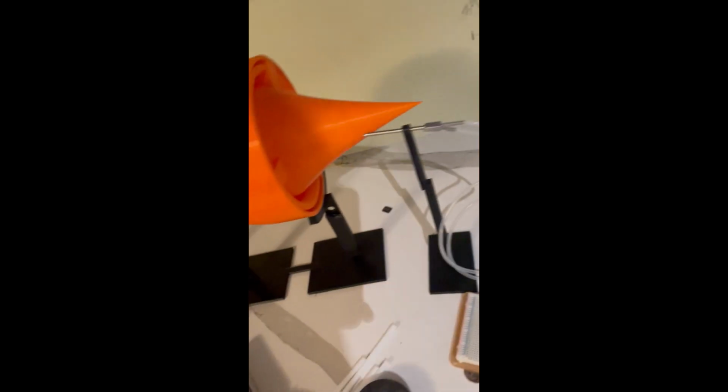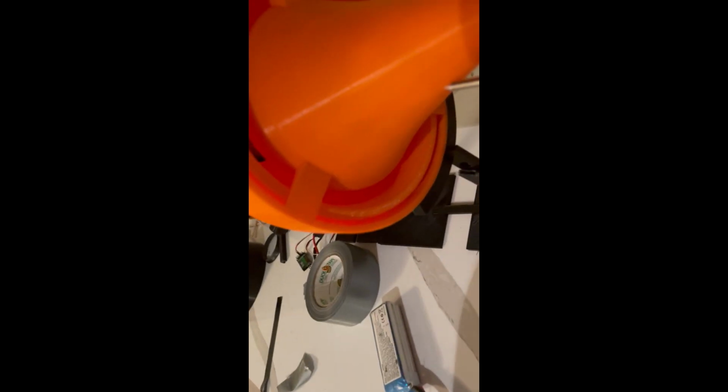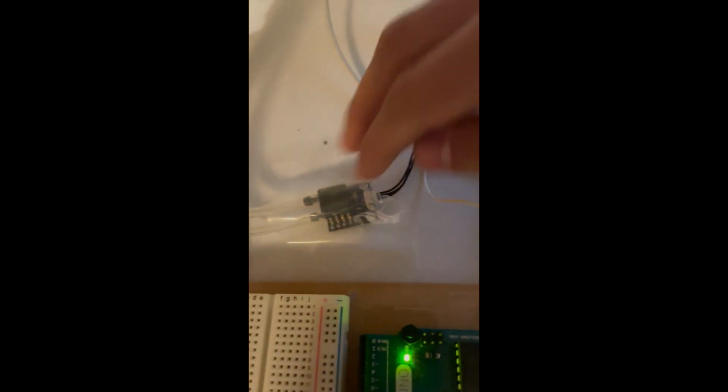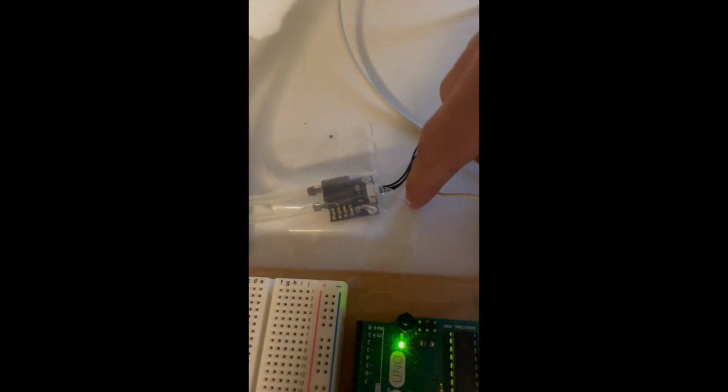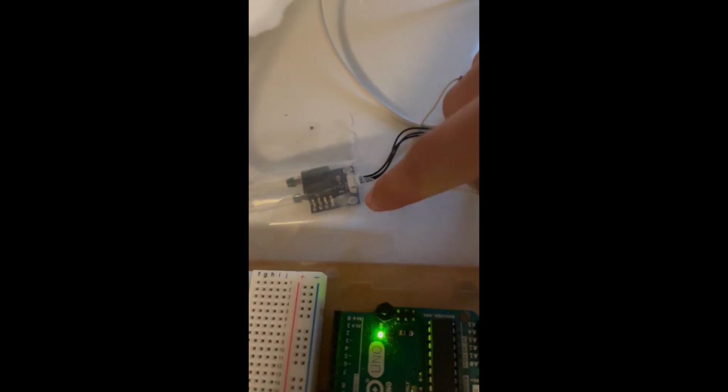And now the data that I'll be collecting will be from this pitot tube that I found online. So this is a small pitot tube that is used on RC airplanes, but it is accurate enough for me to collect data that will accurately show the differential pressure around different parts of my nozzle. And I'm using an Arduino, which will receive a digital signal from this pressure sensor, which has an analog to digital converter, or ADC, inside.